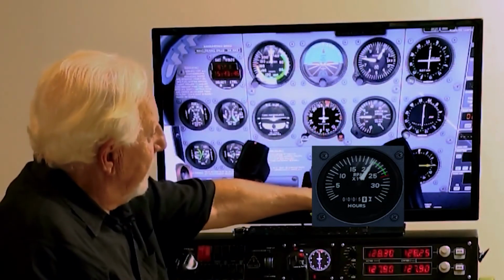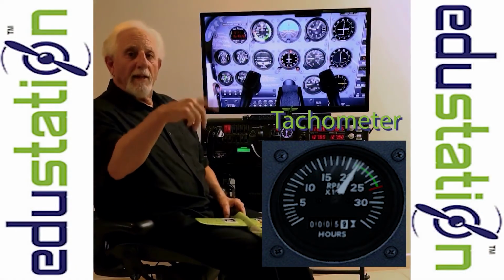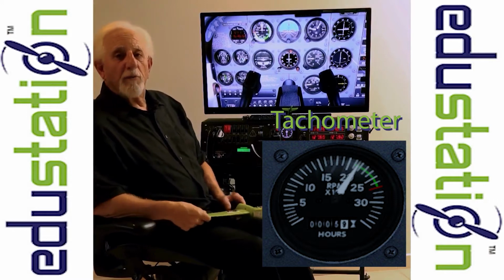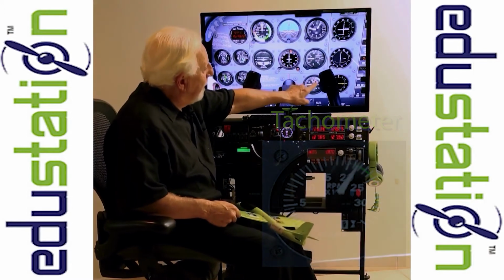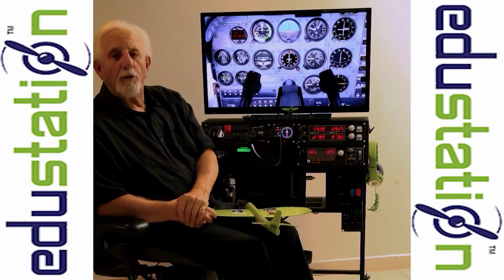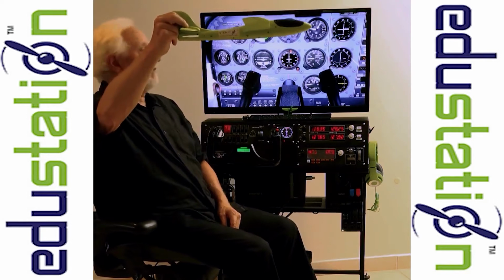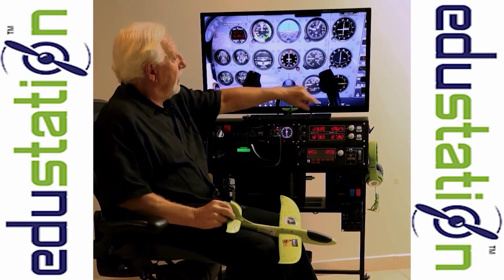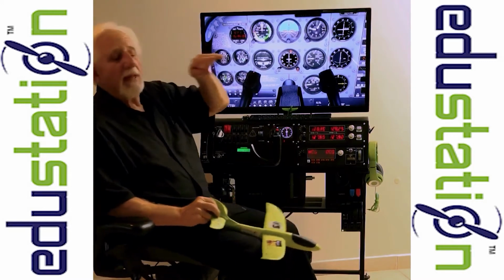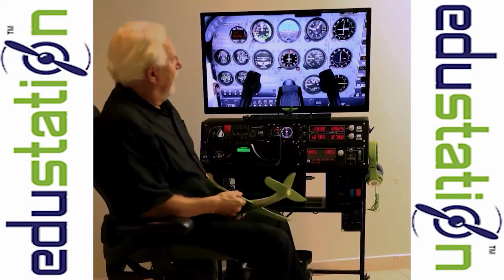The last instrument is the tachometer. And the tachometer is telling us how quickly the engine is spinning in revolutions per minute, RPMs. When we take off at full power, we're going to be at about 2,500 RPMs. But once we climb up to, let's say, 3,000 feet and we level off, we want to pull that power back to 2,300 RPMs, and that will generate a cruise speed of about 100 knots.